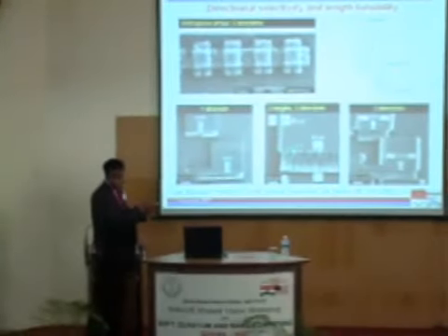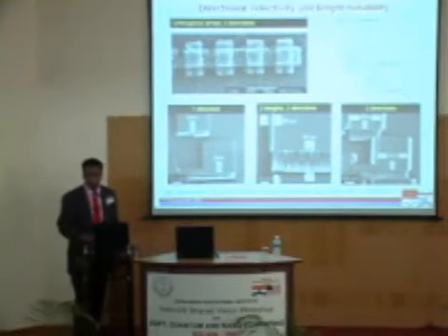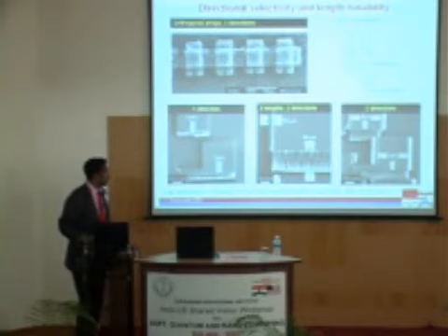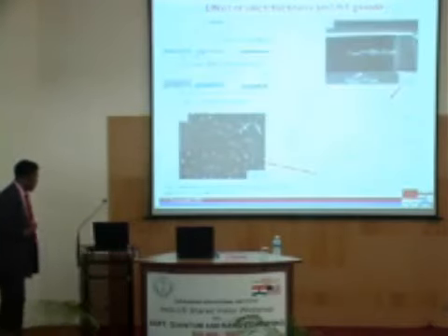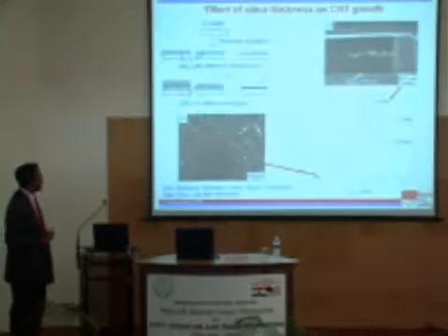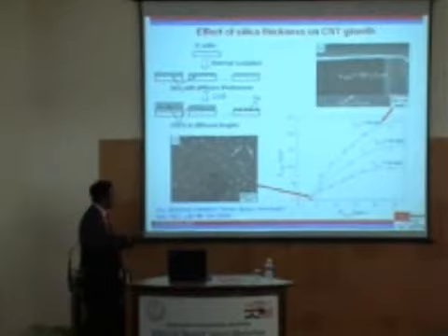Additionally, you can also notice that by putting different amounts of gold on different faces, you can also control the length. Because in a device structure, obviously you don't make devices with all the same length of the elements. You need different elements with precise control. Okay, there is another very interesting way in which you can control the lengths of carbon nanotubes, and that is very non-intuitive. I'm going to very briefly touch upon this.